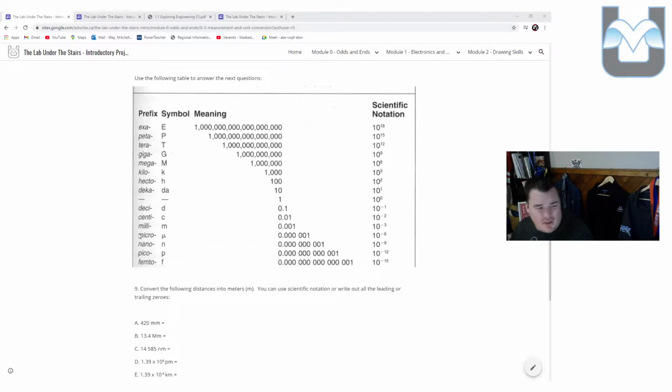Those are very different things when we start talking about electronics, and you should really know what those are. Inevitably, somebody has an LED in this class that doesn't turn on because instead of putting on a 1 kilo ohm resistor, they've put a 1 mega ohm resistor on it and they didn't notice. Happens more often than we'd like to say.